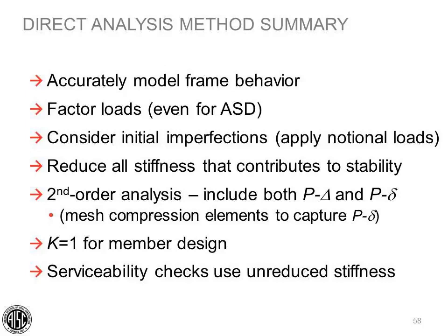Perform a second-order analysis that includes both P big delta and P little delta effects. Mesh the compression members in order to capture the P little delta effects. K equals 1 in all member design equations. And last, check serviceability using the nominal unreduced stiffness properties.